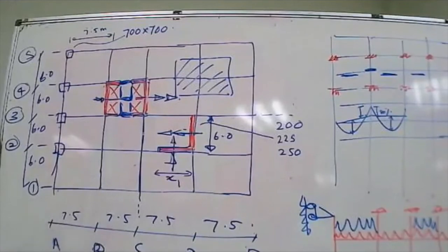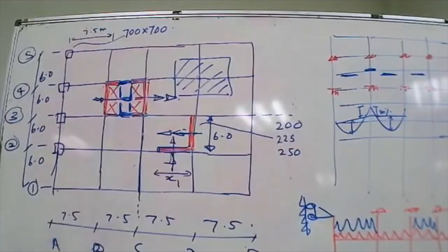Okay, so thank you, sir. Another question, sir. Sometimes when we change the redistribution level, the point of contraflexure changes. How can we get some idea? No, it's only a minute change. Eurocode gives a lot of guidelines on those things.